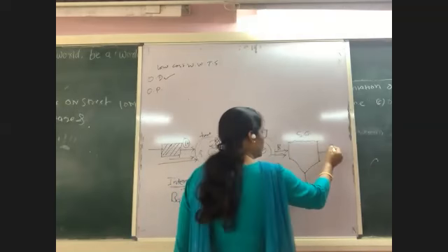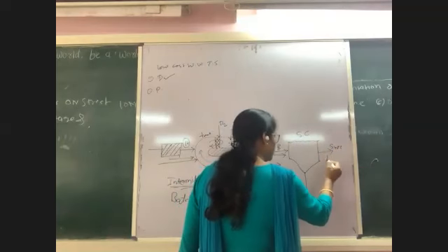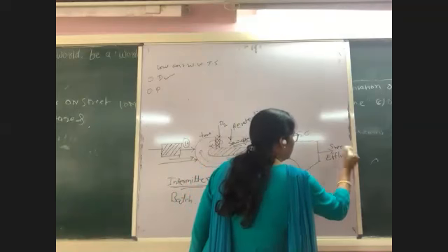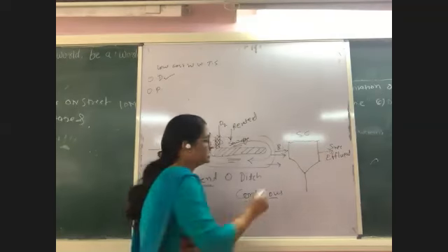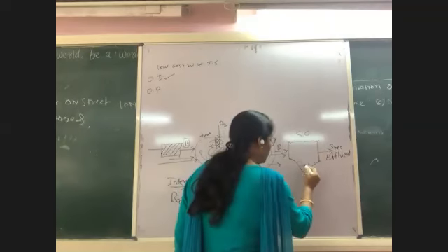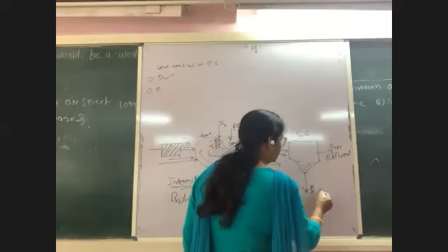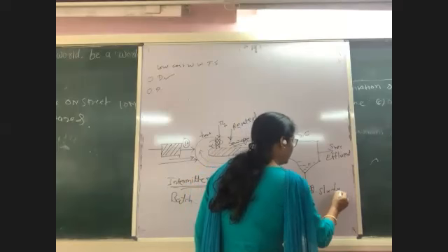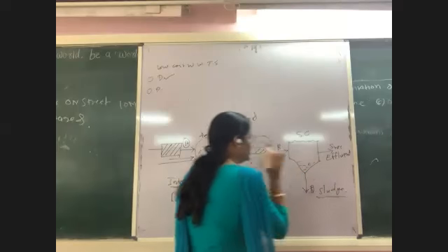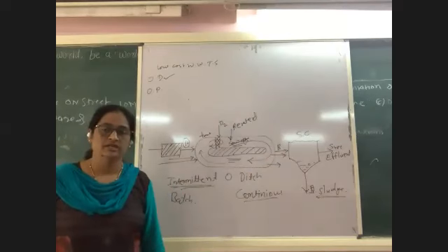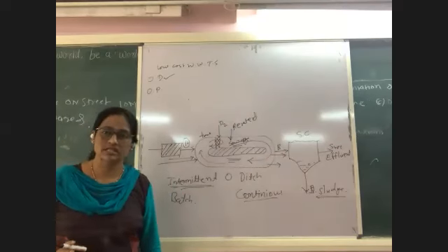And then the supernatant, or the effluent as we usually call it, will be removed from the top surface and the settled sludge will be removed from the bottom. So this will be the activity performed in a continuous type of oxidation ditch. This we discussed in the last lecture.